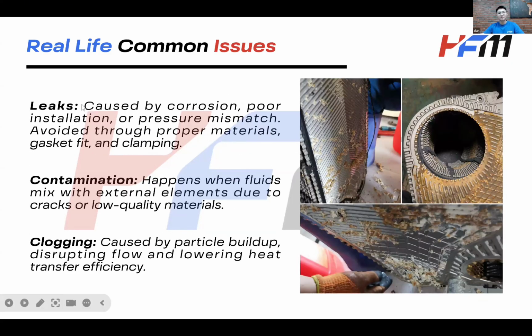Okay, the second one is the leakage. The leakage is often caused by corrosion, incorrect installation, or the application of inappropriate pressure, causing one or both fluids to leak. And therefore, it is necessary to choose the right material for the plates and gasket.